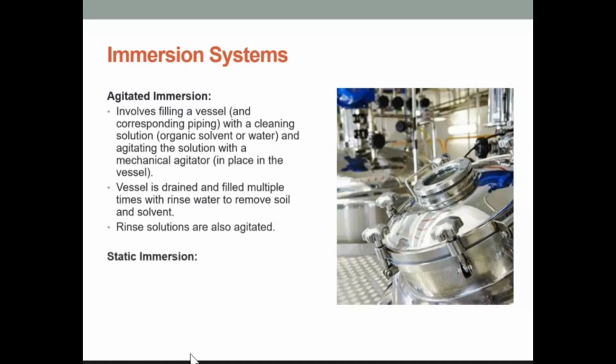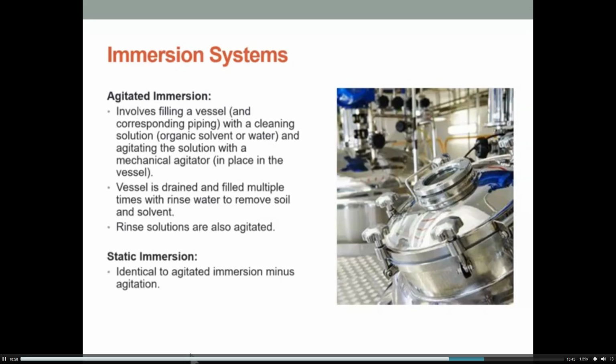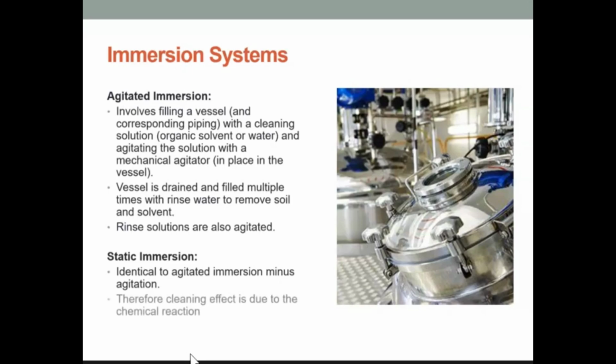The second type then is your static immersion. So this is identical to agitated immersion, but you're minus the agitation. So you're filling your vessel with your cleaning solution, you're draining it and having your rinses. Therefore, the cleaning effect is due to the chemical reaction alone and is not dependent on the agitation of it.